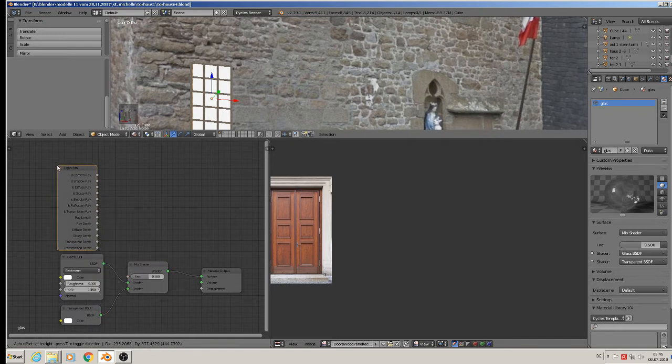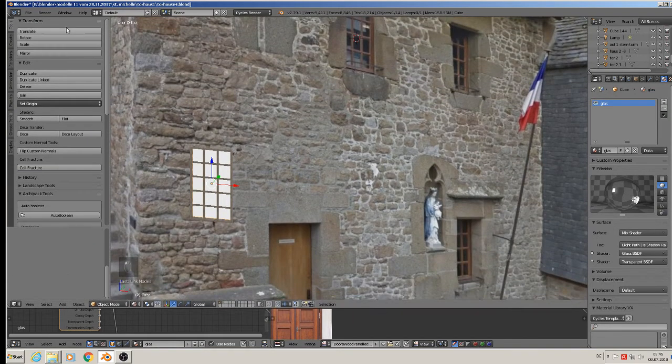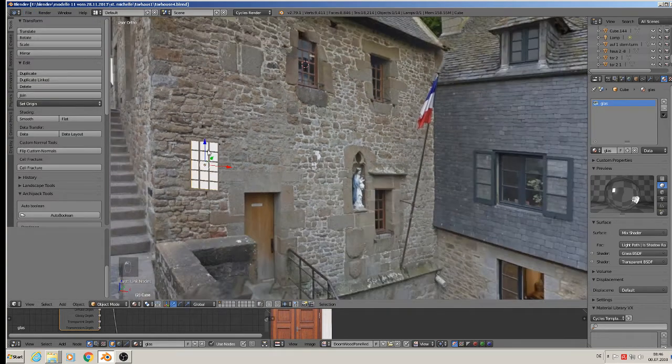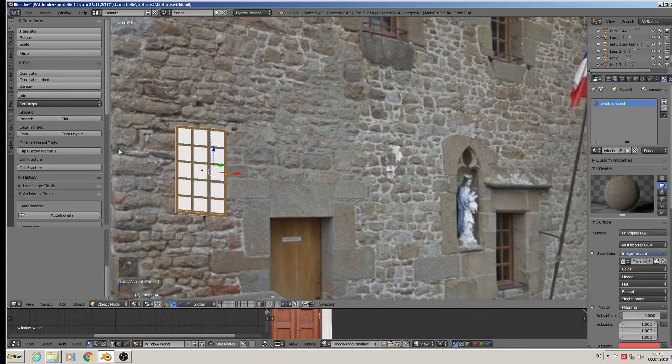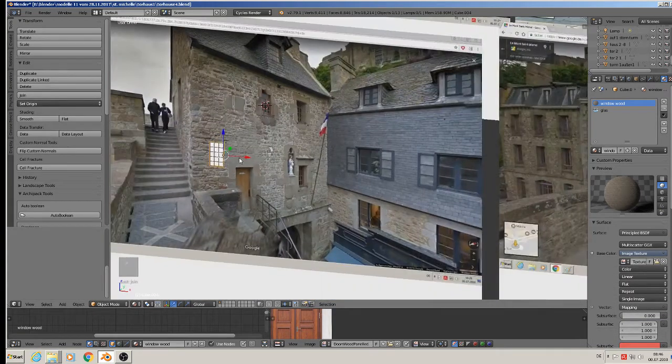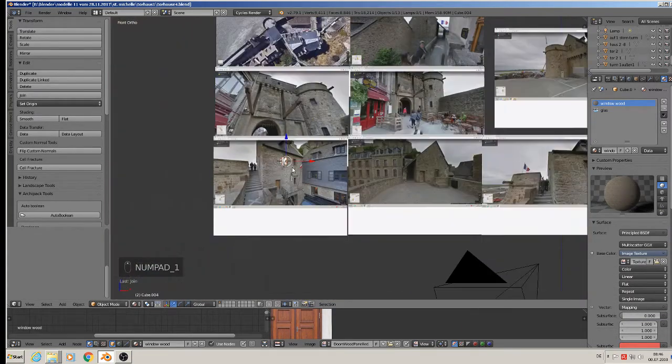That is the way the light should go through an object, and we want that no shadow should be there. That we take as a factor, and then we have a clear glass material. Good, done. File, save. Now we join them both together, the glass and the window. So we have our glass window.